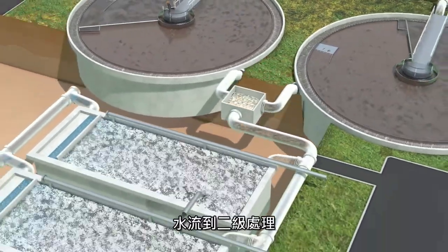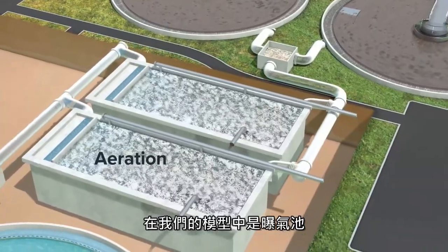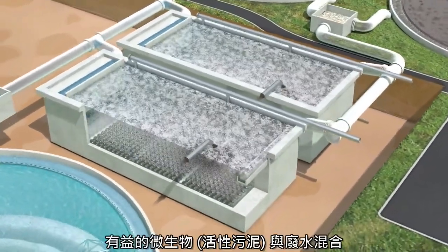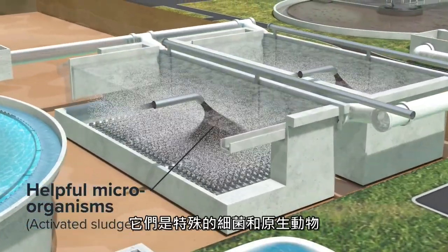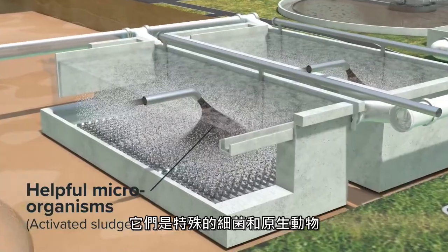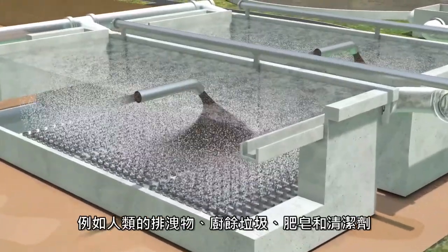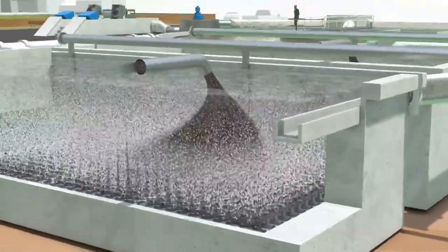The water flows to secondary treatment, which in our model is an aeration tank. In the aeration tank, helpful microorganisms are mixed in with wastewater. These are special bacteria and protozoa that consume biodegradable waste products such as human waste, food waste, soaps, and detergents.